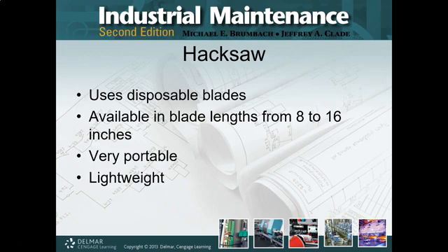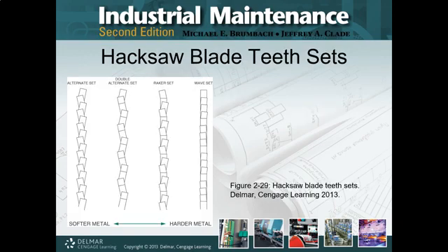The catch is where most people tend to screw up is they push too hard on the blade and they go too fast. Both of those things wear out the blade really fast, and also make cutting an absolute nightmare. As I kind of joke, it's supposed to be relaxing and therapeutic to be using a hacksaw, because you just take a deep breath, you relax, let the saw do the work, and you just take your time. Do a nice rhythm, use the entire length of the blade. You've got a full blade, use it, and away you go.